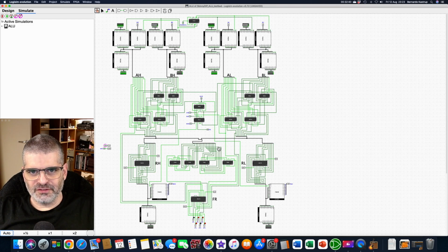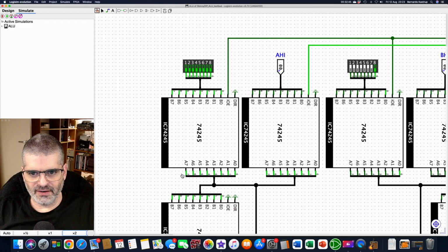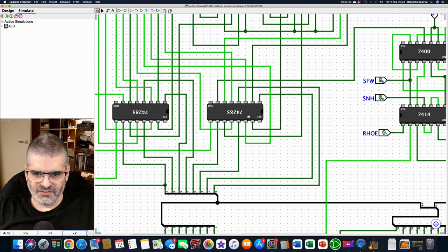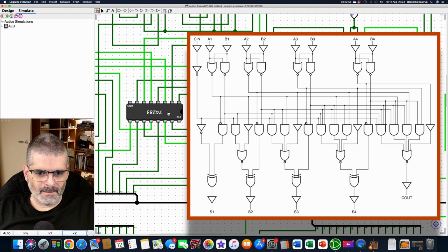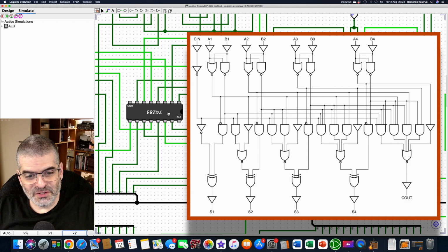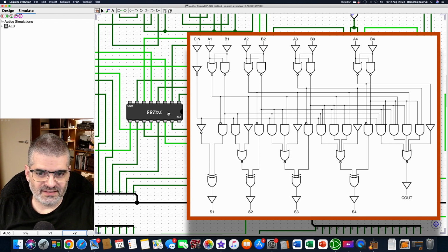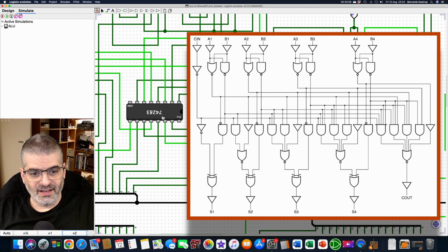It's very nice of this tool that it has models for all these chips. Some of these chips are fairly complex internally. I mean, the 74283s, the ALUs, they have dozens of gates inside. It's very handy to have this model, and this is another reason why you definitely don't want to do a schematic based on individual gates. It's a waste of time and defeats the purpose, because we know this chip works. Why am I going to go through the trouble of putting together the dozens of gates inside this chip to verify that they work? I know the chip works.